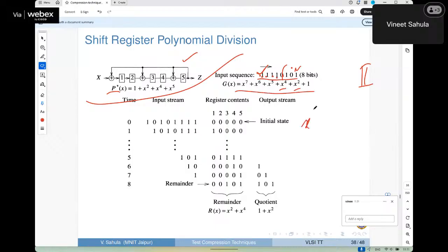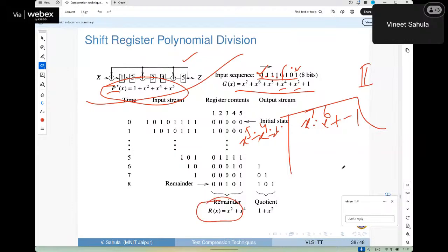I take this polynomial and divide it with this P star X. And I will get this remainder here. That is what it would mean if I take this practically. This is a sequence. I push it in and do these computations practically. So this is my method 1, polynomial. This is method 2, bitwise. I take bits in. I keep doing XORing.